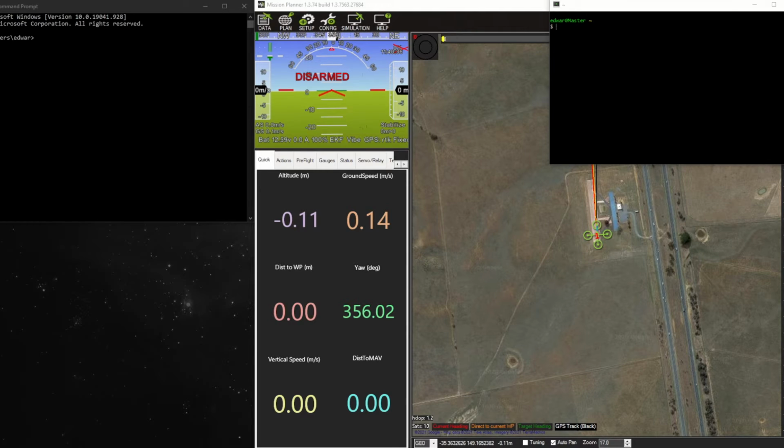All right, welcome to the next part of the demonstration. Here I'll be presenting the simulated vehicle and the steps taken to launch the software in the loop program. First step is to locate the sim vehicle program within the Cygwin terminal. Cygwin terminal is a Linux-based terminal used to launch Linux-based software on a Windows operating system.